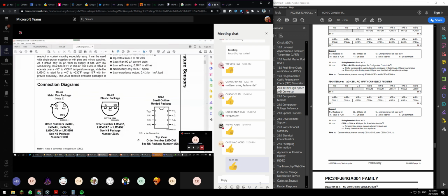And why do students keep burning this beautiful LM35? Because of this word. When they see it like this, they can't differentiate which one is positive VCC and which one is ground. It says bottom view; top view is the other way around. So students keep burning them. They're burning, they're so happy, smoke comes out. Oh yeah, okay, burn. Then they return it and repeat the process many times. Then only do you know that, oh dear, it is this word.